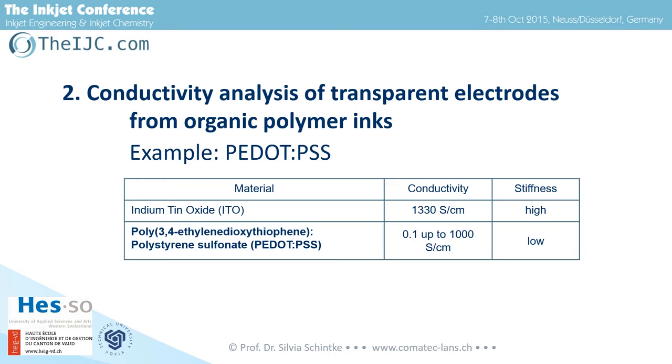You will have contact resistance contacting the layer. So often in electronics, also in the semiconductor industry, for example, people use 4 probes. 2 probes to have the current, and then 2 other probes to measure the voltage drop in between, which already increases the precision of the measurements and avoids these questions of contact resistance and resistance of electrical probes.